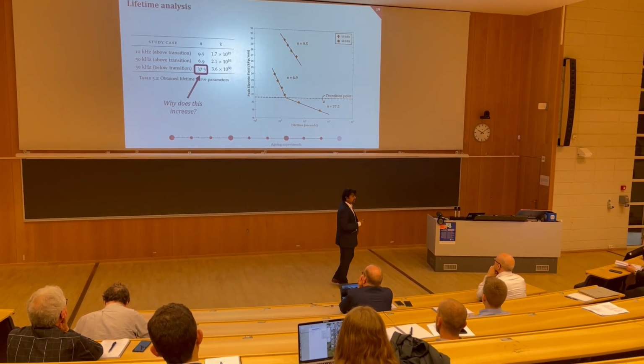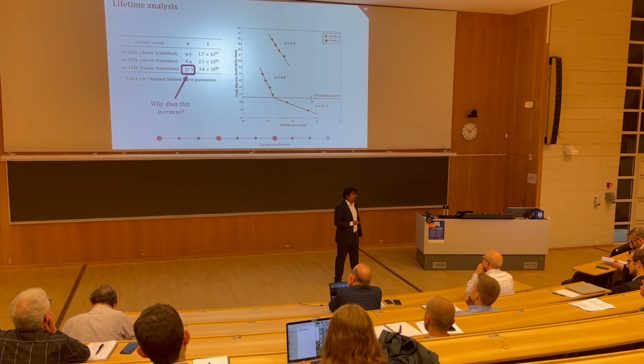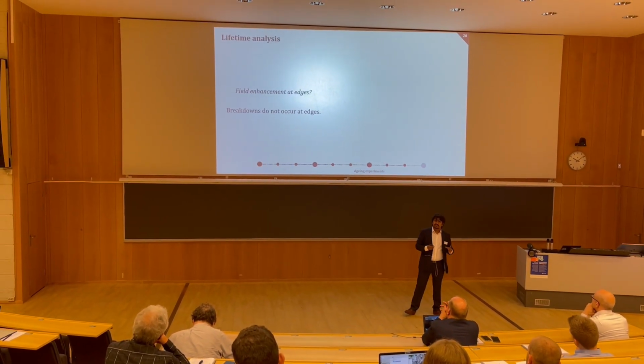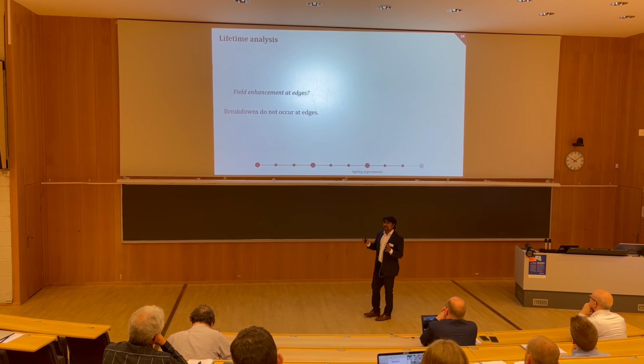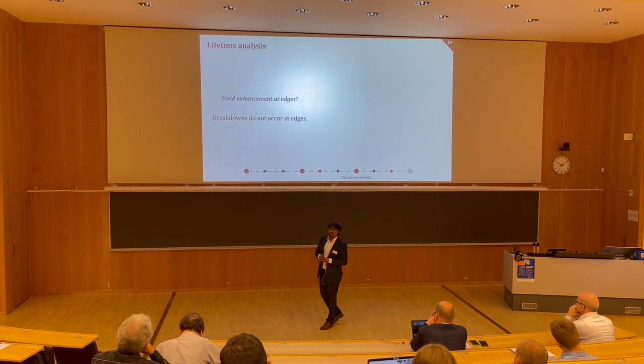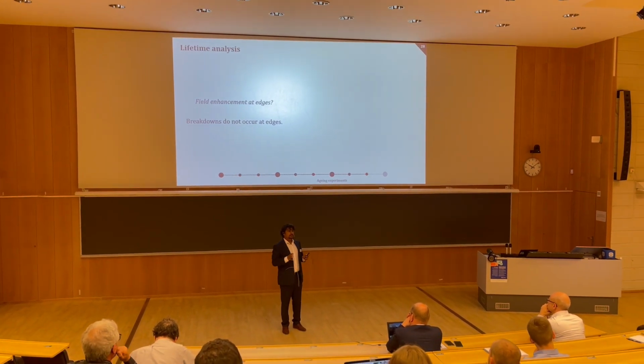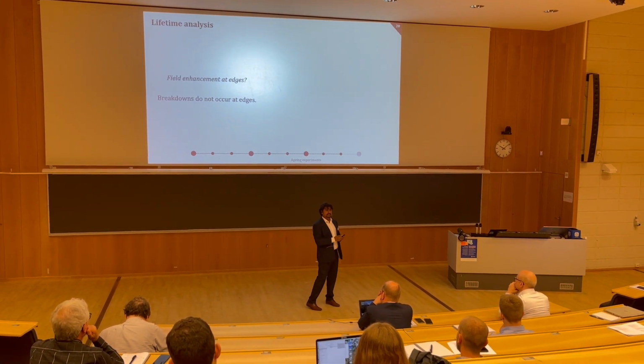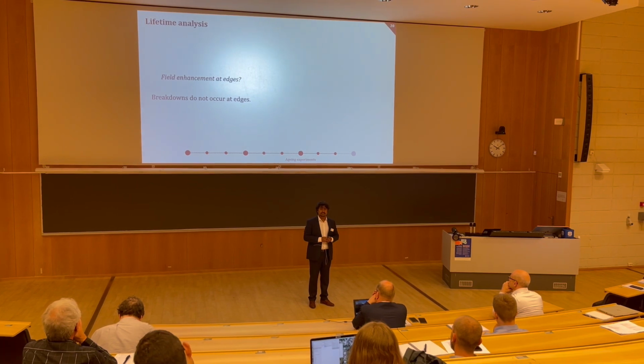And then we started thinking about what could be the cause for this. Well, the first hypothesis was that maybe there could be some field enhancement at the edges that is causing this issue. But then we also observed that no breakdowns happened at the edges. They were all at dead center in the insulation samples.